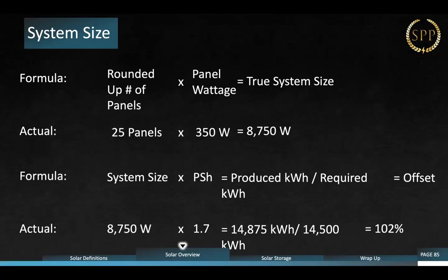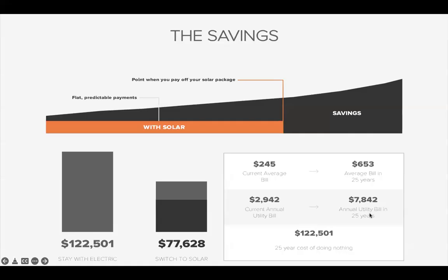Most utility companies will buy back up to 110%, and we'll go into more detail about this later in the week, 110% of the customer's usage for the year, for the last 12 months. Some utility companies go up to 120%. Those are typically co-ops and some of the very, very large utility companies. We're looking at average across the board is 110%. So we usually build it somewhere between 100 to 110% to give them a little bit of wiggle room.